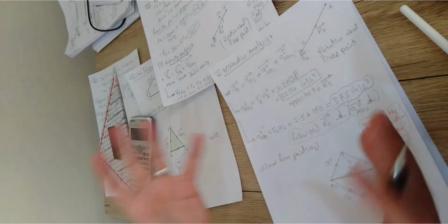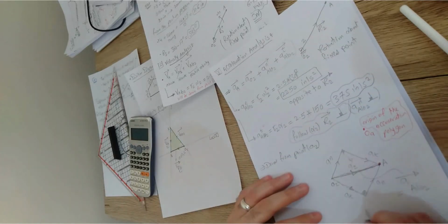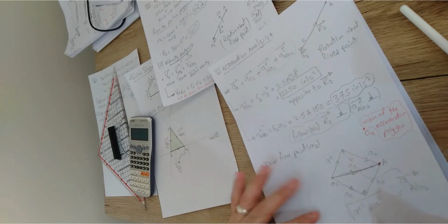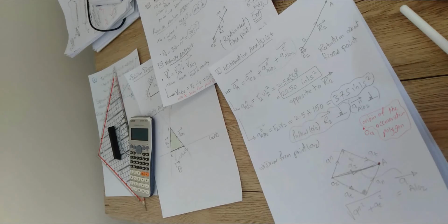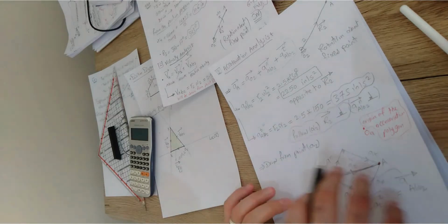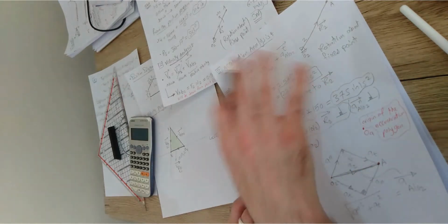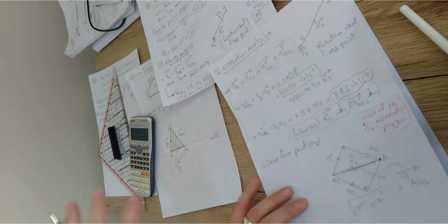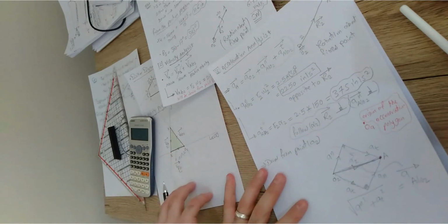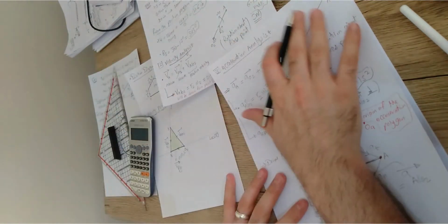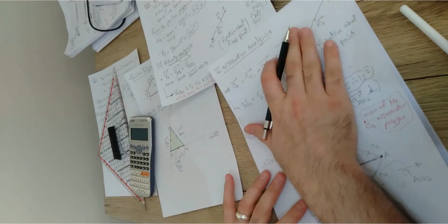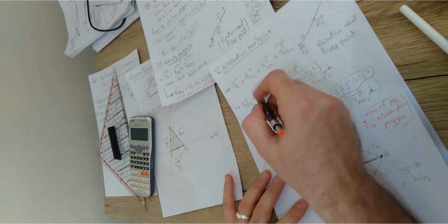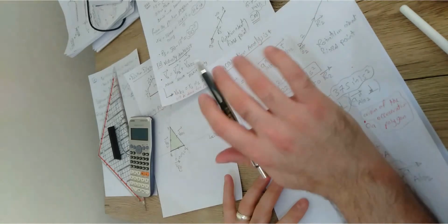This is the magnitude, which is the square root of the A normal squared plus the A tangential squared. This is the resultant, because you have 2 components and this is the resultant of both of them. We're going to do the same over the acceleration polygon or acceleration diagram. This is the plan for how we're going to draw the acceleration components for a link that does rotation.